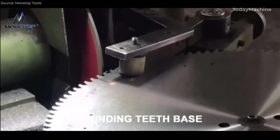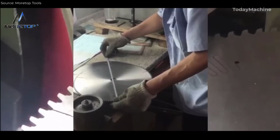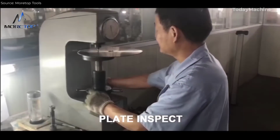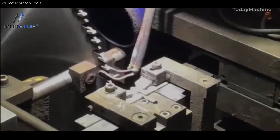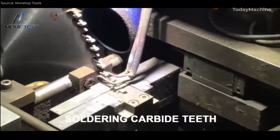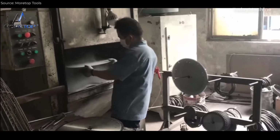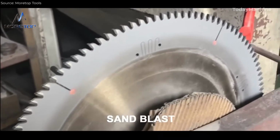Materials and coating technologies. One of the most significant advancements in circular saw blade manufacturing is the development of new materials and coating technologies. High-speed steel, HSS, and carbide-tipped blades have become industry standards due to their superior hardness and resistance to wear. For instance, carbide-tipped blades can maintain sharpness up to 10 times longer than traditional steel blades, significantly reducing downtime for resharpening.